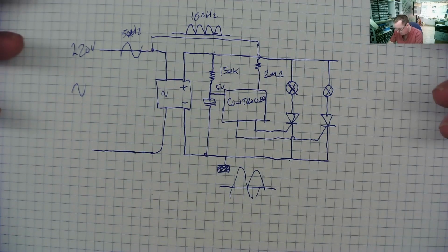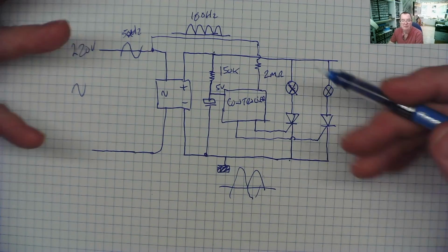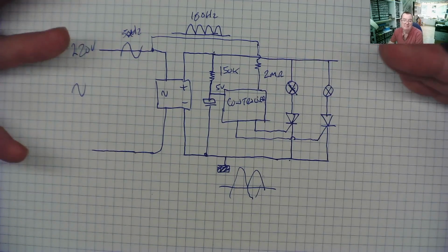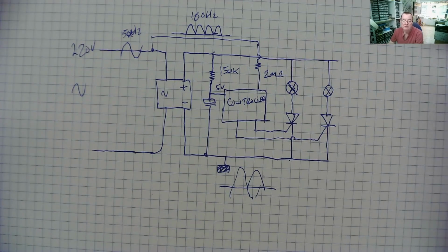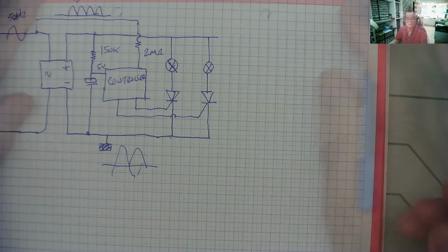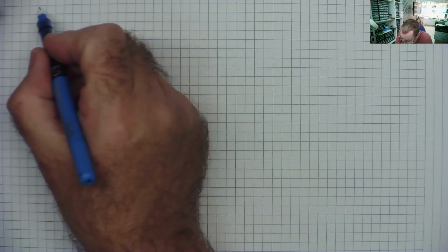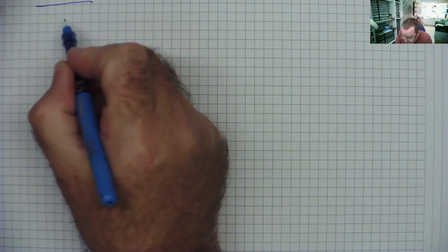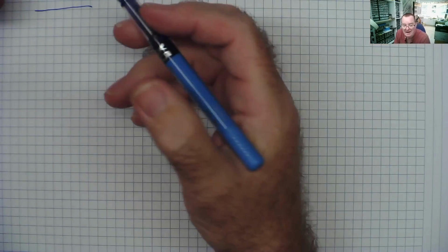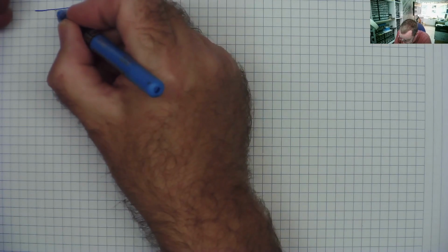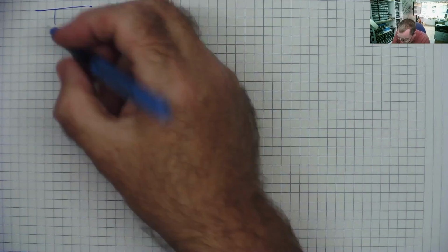Let's have a look now at Triacs and Diacs. Unfortunately now we know all about Thyristors or SCRs. We don't need to know very much more. So a Triac then. Basically it's just two Thyristors connected in anti-parallel. Anti-parallel means that they are opposite way round to each other.